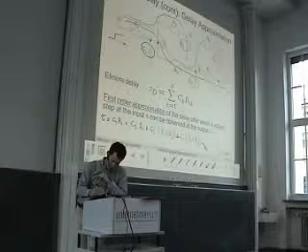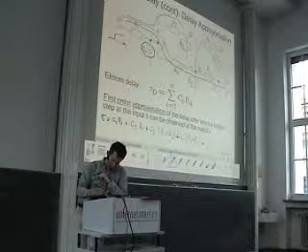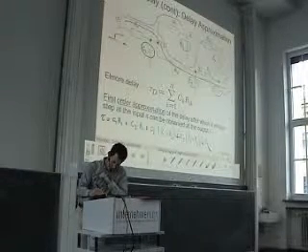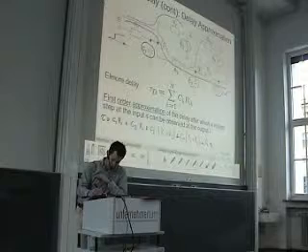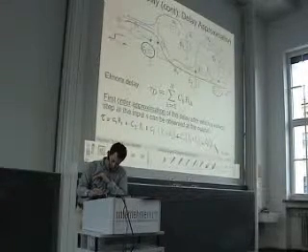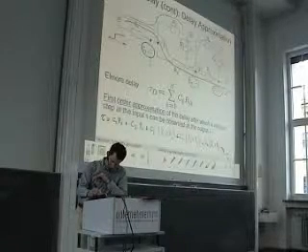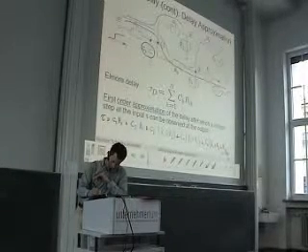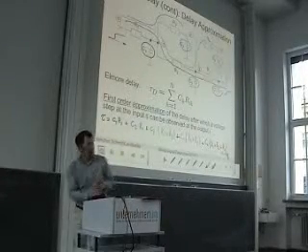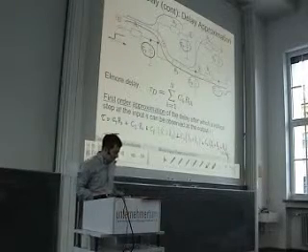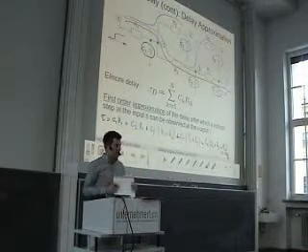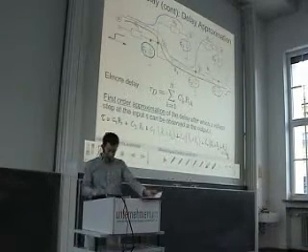And finally, our last cap is CI. For CI, of course, there is only one path left. This is R1 plus R3 plus Ri. This is the formal definition, and now we can apply this to our resistor string DAC.